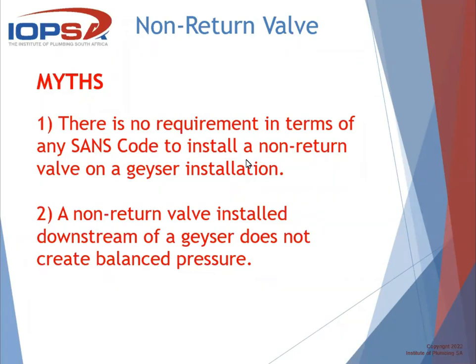And so you can have this very careful, controlled circulation, ensuring that there's hot water at the last point, but also ensuring that you're not using tremendous amounts of electricity. And also you can couple that to a timer so that that pump is off completely between certain hours. So in other words, it can be set up to pump only between 5 p.m. and 10 p.m. when everybody's home and wanting to use hot water. Then for the rest of the day it's off. Fine, no problem. That's controlled.